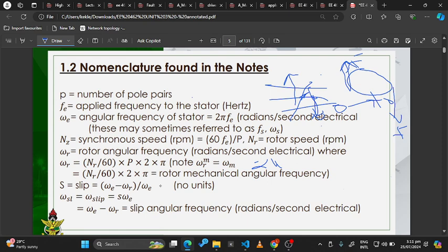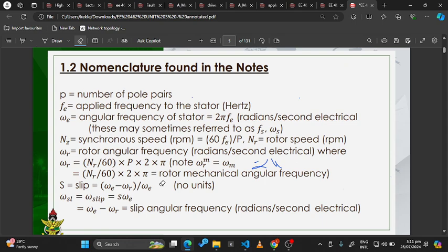Now let's go to electrical speed and mechanical speed. Let's look at the electrical angle and the mechanical angle. This thing has been confusing a lot of people, so let's address it. If you take a motor or a circle, the total angle we know from mathematics and physics that you can have in a circle is 360 degrees, and this is the maximum mechanical angle you can have.